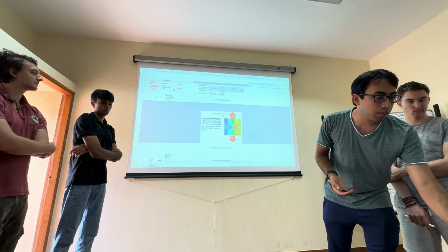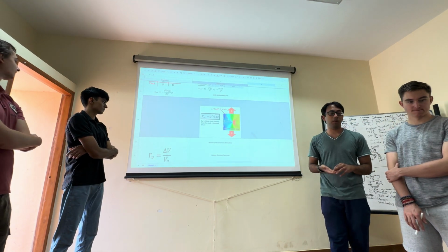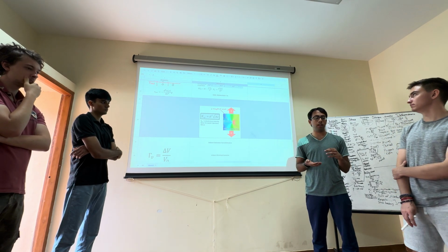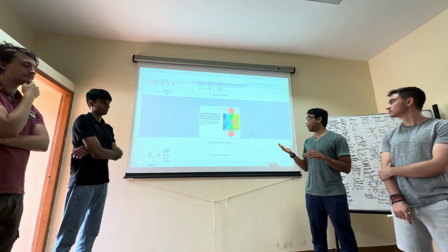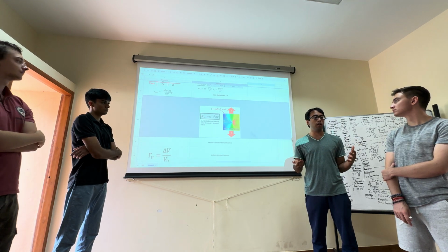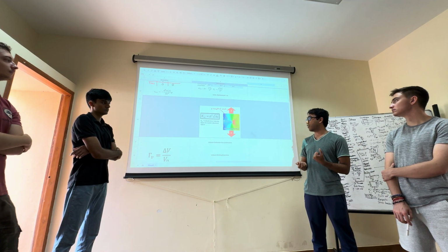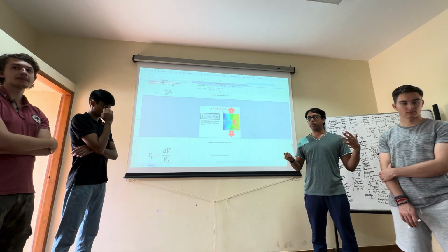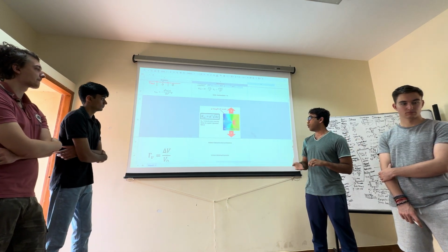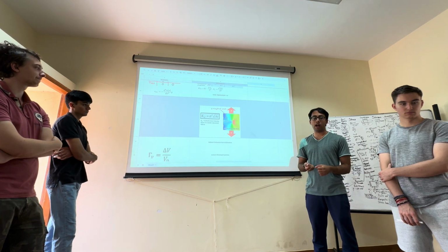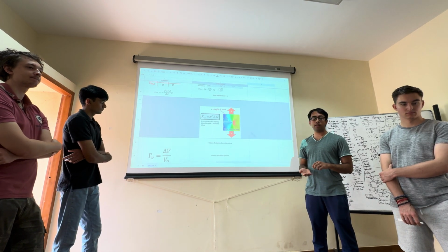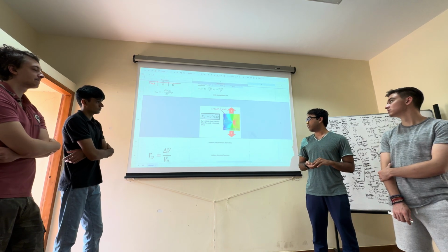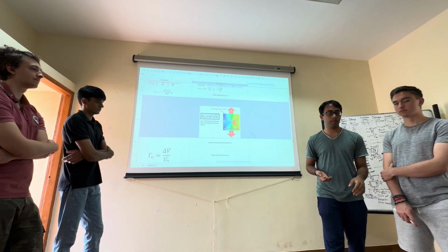Oh, and then next up we have this equation that I included from my MSc materials class, where we talk about how we can actually quantify crack propagation, where we have K1C specifically as a material property, specific to the material, and this is occurring mainly under the condition that it's under tension. That's the basic assumption that we're making here. And the equation you'll see includes the stress, where we're having it in tension, times the square root of pi times c, where c is the length of the current crack. And using this, you can predict future behaviors.